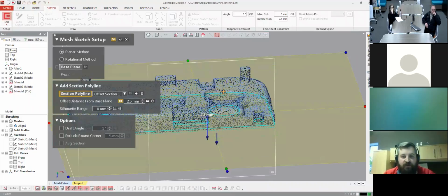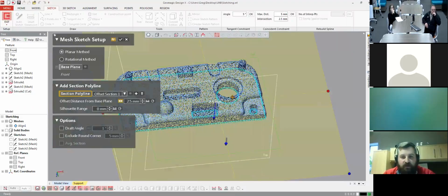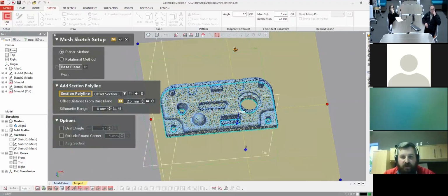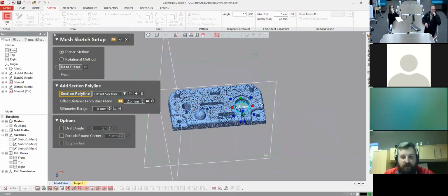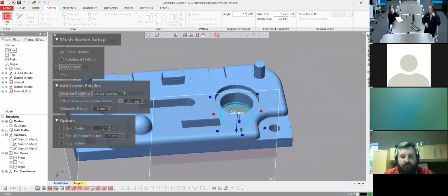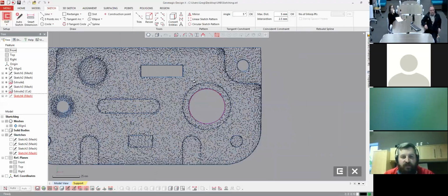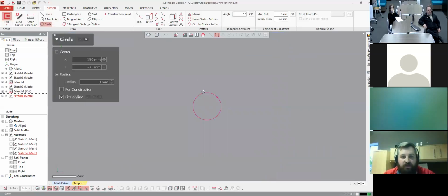All I'm going to do is try to find the center of this feature. One thing that's nice about the sketch function is you can see this giant window. I can actually pull this and move it around so it's singularly focusing on whatever function I want to use, so I'm not grabbing any extra data out in space. So I accept that, and you notice there's no other pink lines, so it's a very concentrated sketch. And I can fit my circle to this, and this is where I want to use construction geometry.